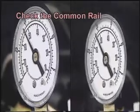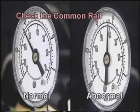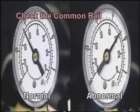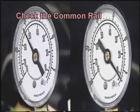However, in a malfunction state, the vacuum is first measured and then the vacuum state erodes slowly, as shown in the right side picture. In this case, the air tightness in some portion of the common rail is defective.